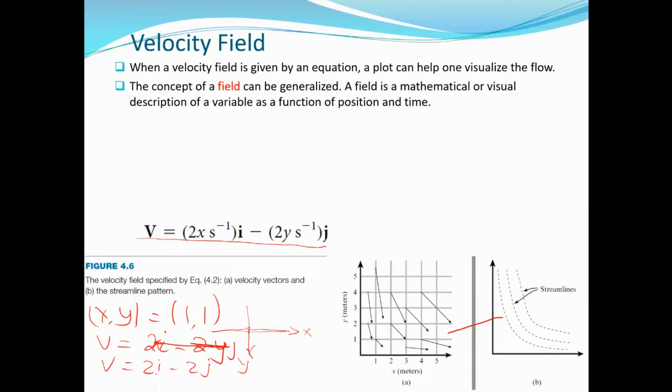Here you can find the direction. The magnitudes are the same, so the direction theta will be 45 degrees because Fx is equal to Fy. So it's going to be something like this, and that is why we have this particular value here.